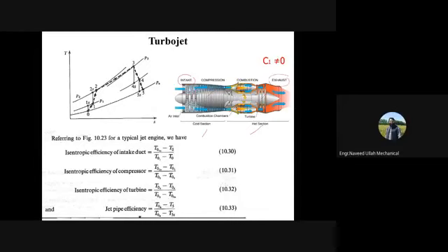Exhaust is actually moving through the nozzle and intake is in the diverging duct. Okay, in the diverging duct we do the intake. Why diverging? Because it actually increases, here also. If you look at this thing, what is the velocity in the turbojet? Now, inlet velocity you cannot neglect, because the turbojet engine is moving at a Mach number, subsonic maybe, or even up to sonic speeds. But 340 meters per second, 200 meters per second is not negligible as compared to jet speed.